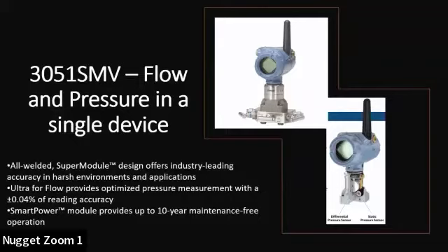In general, you can set these up to transmit anywhere from 1 second to 60 minutes. However, on a leach pad where we're trying to cover long distances, we usually do about a 1 minute update rate. But if you think about it, normally you had no measurements up there. Now you're going to a 1 minute update rate.